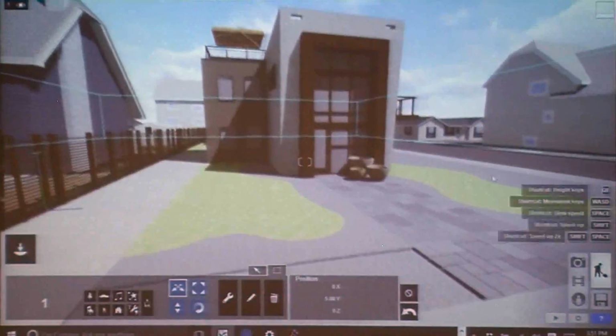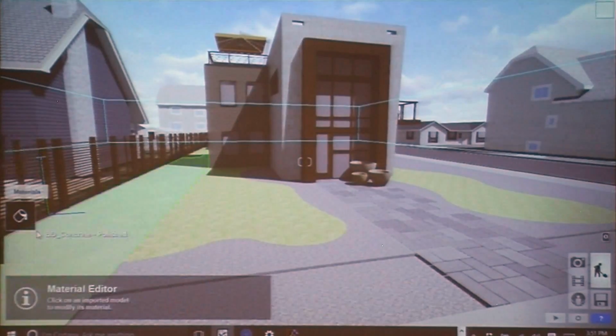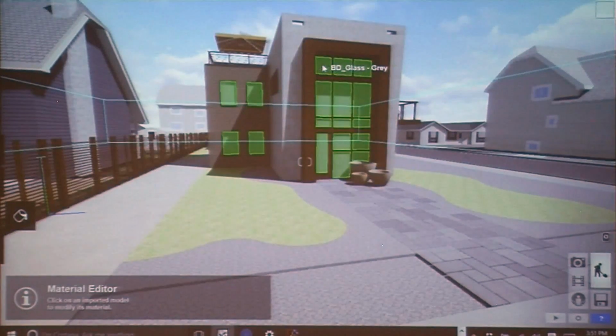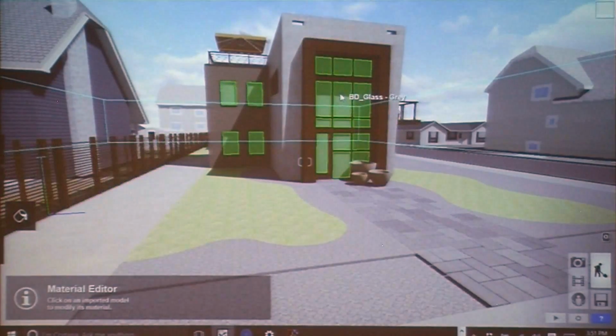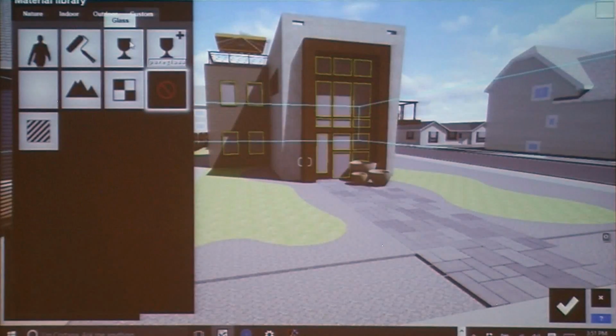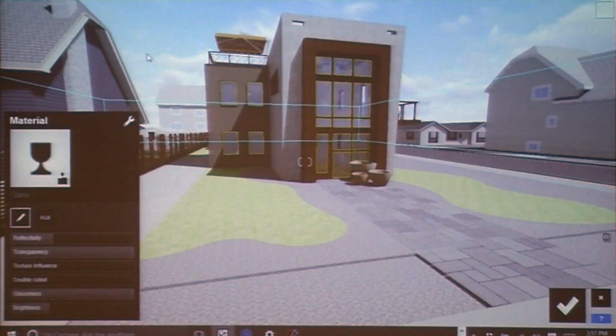So over here we've got our materials dialog. I click on the glass. So you can see that this is reading all of your SketchUp materials. I'll click on the glass and then choose Lumion Glass. All it does is just reassign that SketchUp material to be a Lumion material. This is a live link. If I were to go in and keep adding windows and painting that glass, all I have to do is refresh my model in Lumion and it just updates.